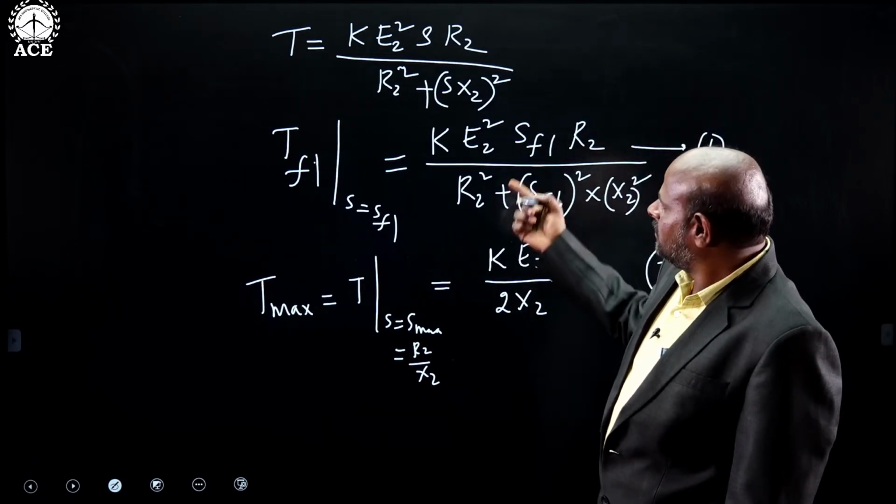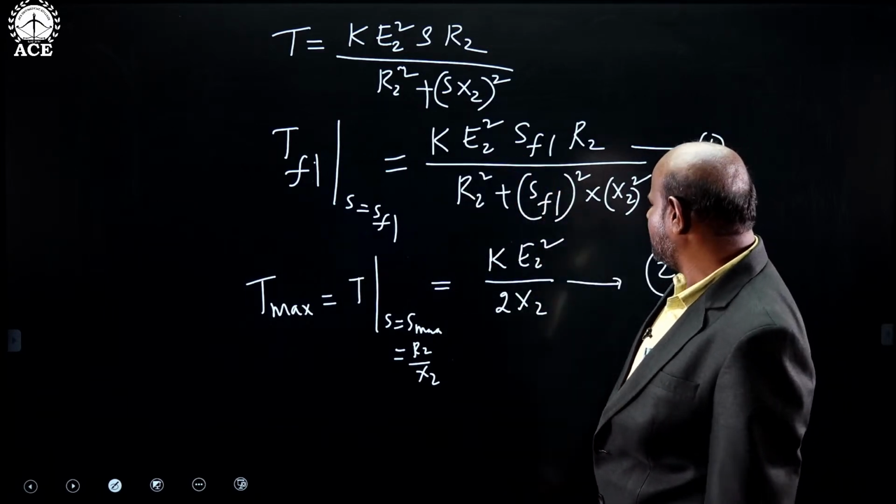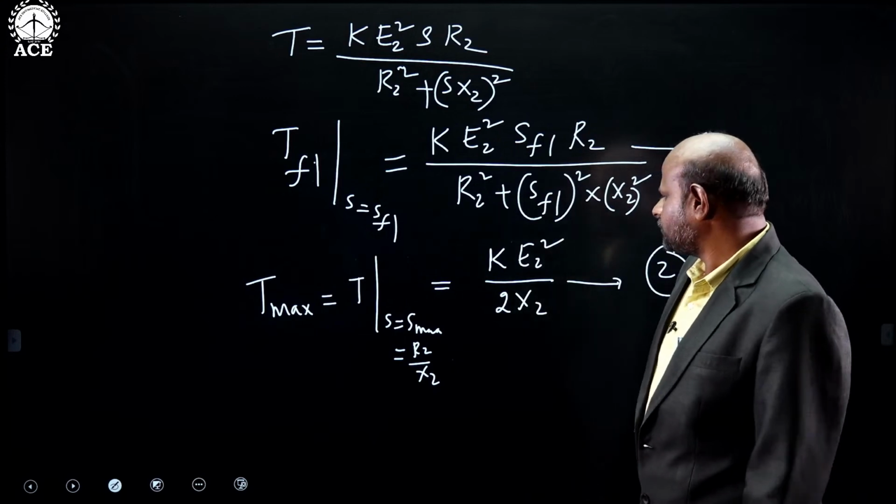He is asking for the ratio of full load torque to maximum torque. Just divide equation 1 by equation 2.